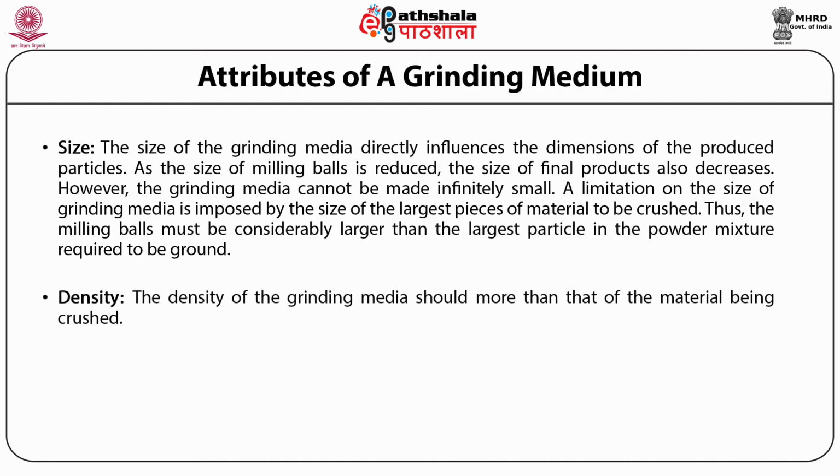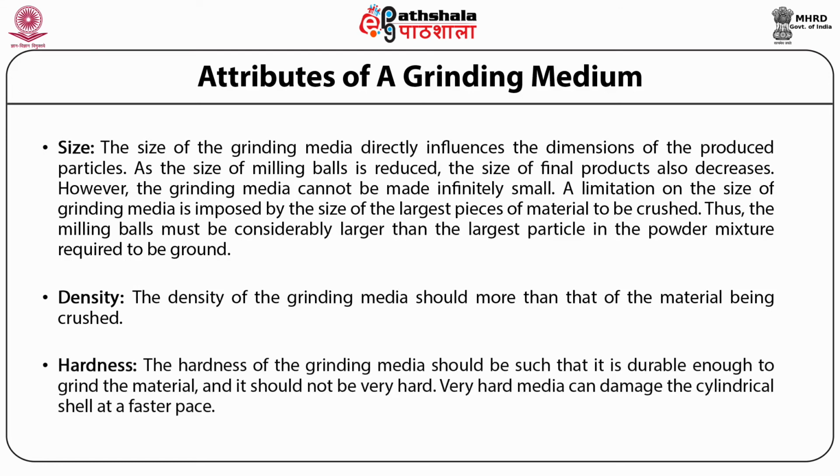The second property is the density. The density of the grinding media should be more than that of the material being crushed. The third important property is the hardness. The hardness of the grinding media should be such that it is durable enough to grind the material, and it should not be very hard. Very hard media can damage the cylindrical shell at a faster pace.